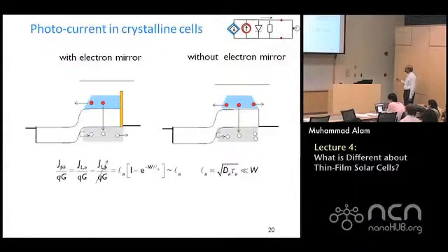And when this current is added to that current, it will show there is no difference whatsoever between these two cases. Because who cares whether you recombine right here or you recombine 2 nanometers into the contact? There's no difference. The wrong contact, wrong recombination, so it makes no difference. And this seems very counterintuitive. The blocking layer, in one case, makes no difference.